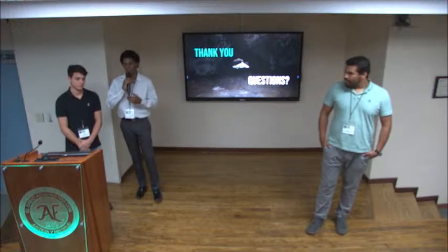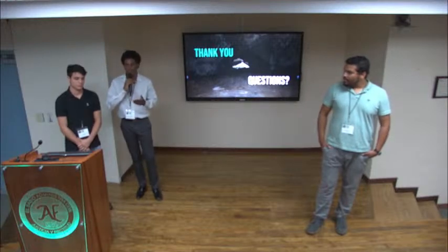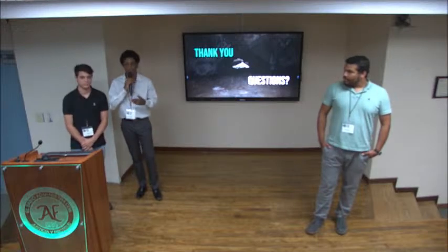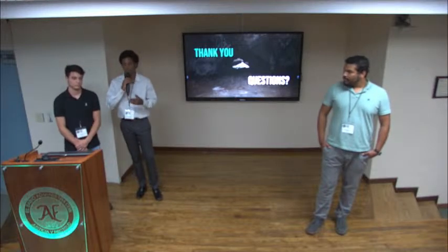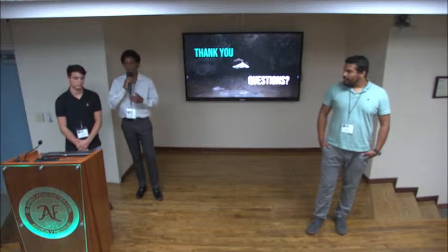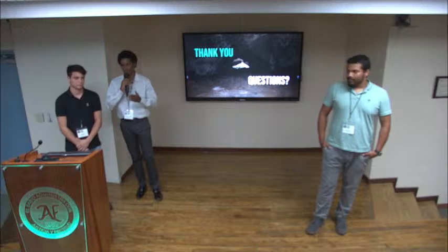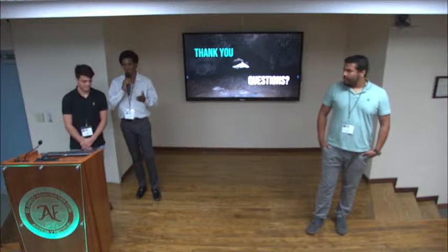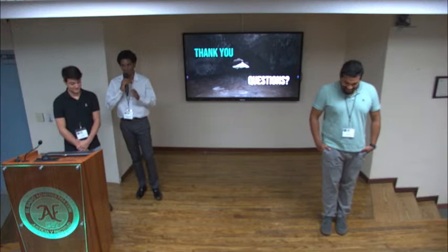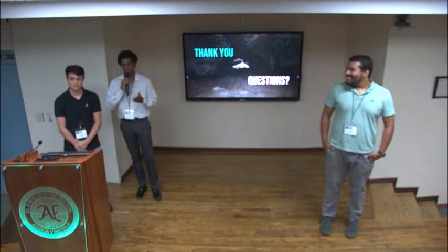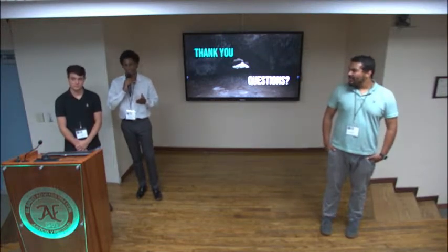And of course, we took precautions in case our system does not run continuously and we lose power, so that our system can reboot once it regains power. And for components such as the real-time clock, which needs to run continuously, it also has a backup battery that lasts way longer than our system would be without power, approximately 10 years, due to the very small power consumption that integrated circuit needs just to keep up the time.